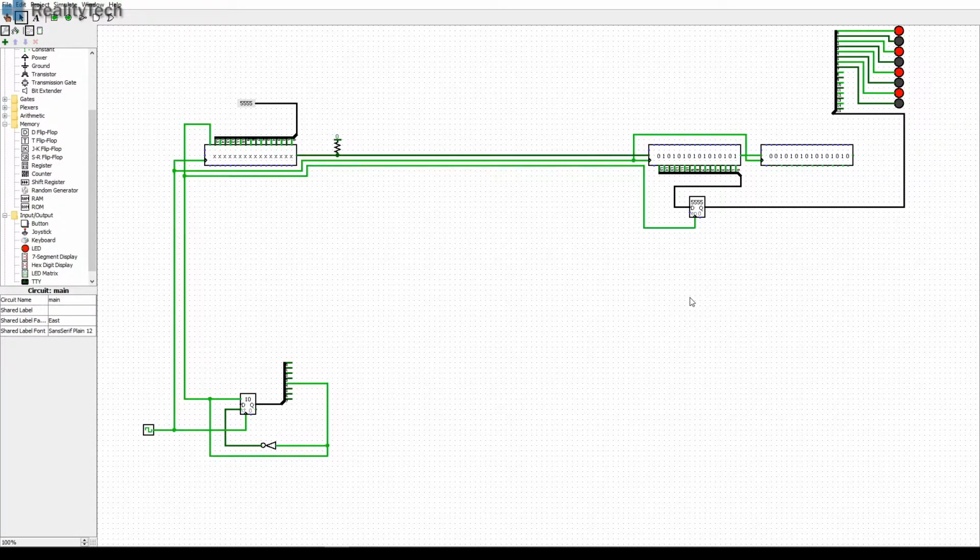This is the basis of something called time division multiplexing. So if we left this running a counter and then drove a multiplexer here, the multiplexer driven by this, and then you've got, I can't remember what the maximum value we can have on 16 bits is off the top of my head, but that gives you quite a lot of inputs. In the case of 8-bit shift registers, you've got 256 analog outputs and only using one analog pin and 4 pins to deal with it.